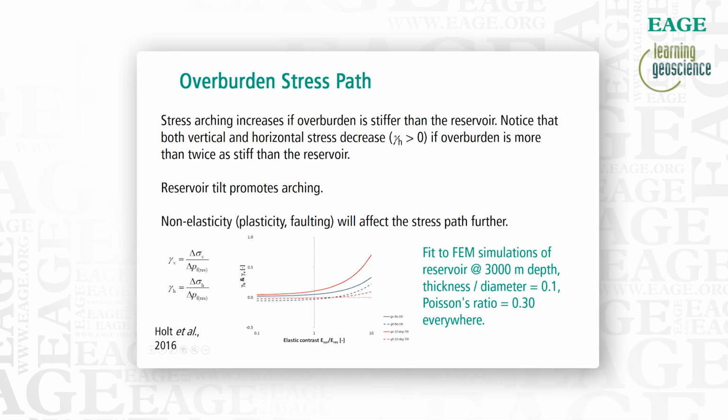Stress arching, as described in the previous part of the presentation, will increase if the overburden is stiffer than the reservoir. In order to do this analysis, we have to use numerical models. For this purpose, we used finite element simulations, and the simulations were done with a reservoir at 3000 meters depth, with an aspect ratio or thickness to diameter ratio of 0.1, and with Poisson's ratio equal to 0.3 everywhere, also